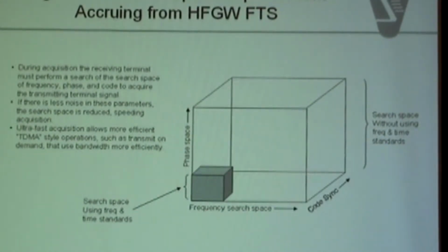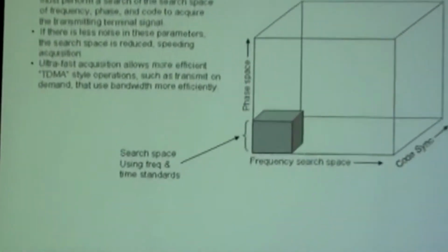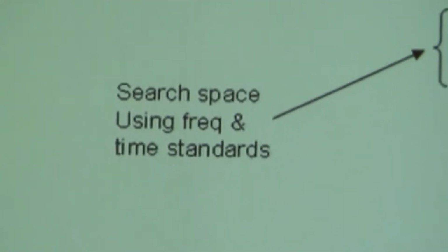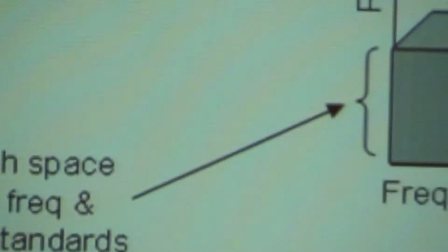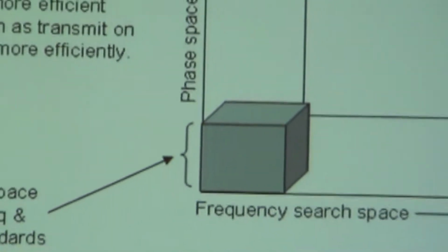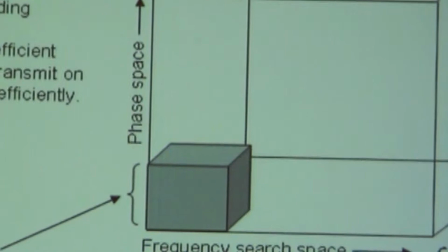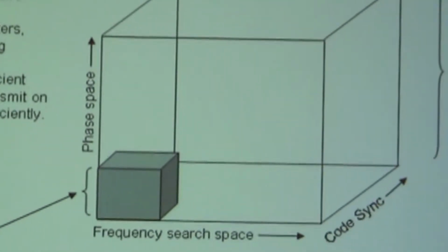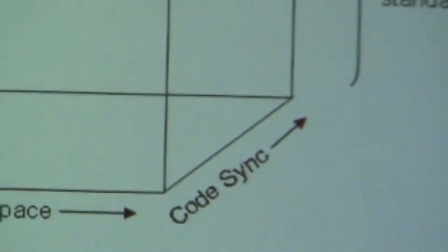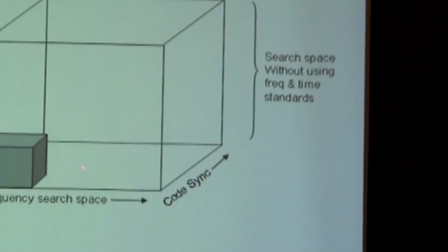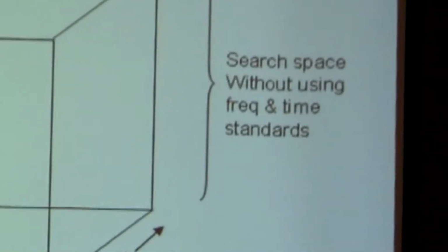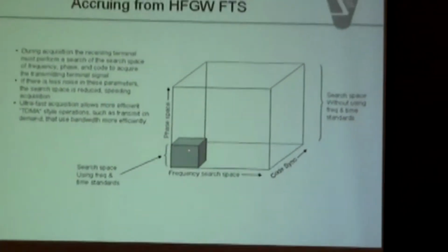where you are with respect to a ground station, for instance, if you're, say, 2 miles from a cell tower, when there's an acquisition code being sent out from that tower, you want to search in code space to lock onto that cell tower. So when you're searching in code space, you know exactly where to search if you know where your location is. It makes it more quickly achievable to achieve code sync.